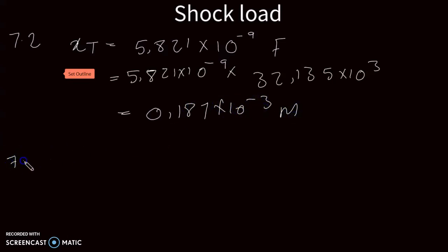Then we go to the next question, 7.3. Calculate the total instantaneous strain energy. Strain energy is given by what? Half force times extension.